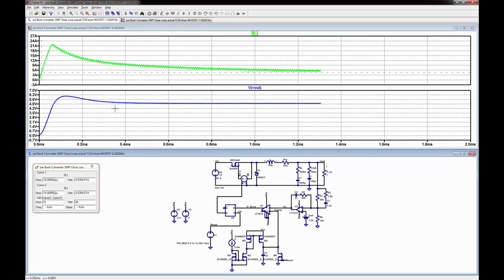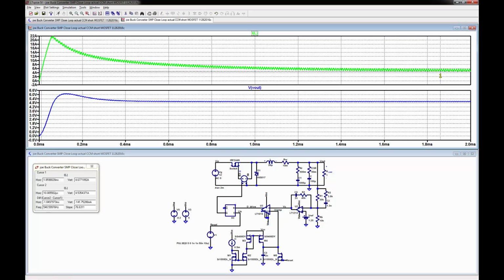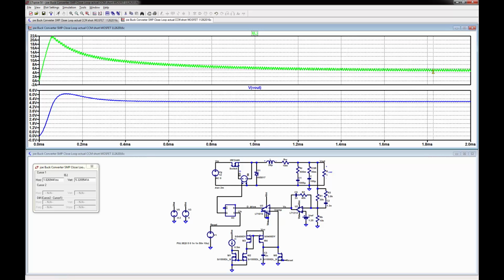There's 1. And there's 2 milliseconds. So now you can see, here's the waveform. We could look at the waveform right back in here, and that's number 1 waveform right there. So let's get rid of the second one. We just want the first one. Okay, so now we just have 1. So we could see our average, which is right in the middle, is the 5 amps.